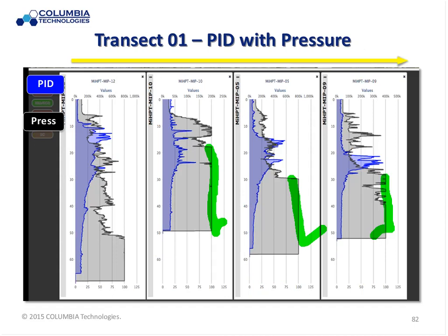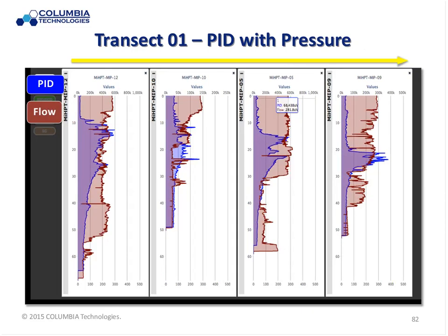Put the pressure curves on there, though, and then you see we've got tight pressure, fairly tight pressure here, tight pressure here. Again, varying widely across the site. This is going to be our transport problem right here. So we're going to screen with our samplers, our monitoring wells, interception trenches, whatever. Those are the depths that we're going to be focused on when we do that.